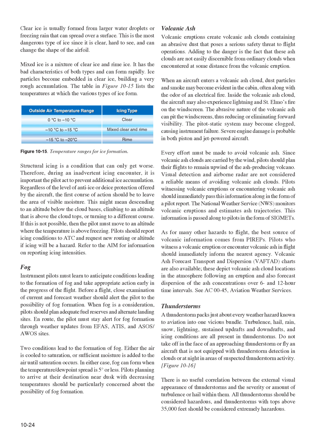Pilots should report icing conditions to ATC and request new routing or altitude if icing will be a hazard. Refer to the AIM for information on reporting icing intensities.